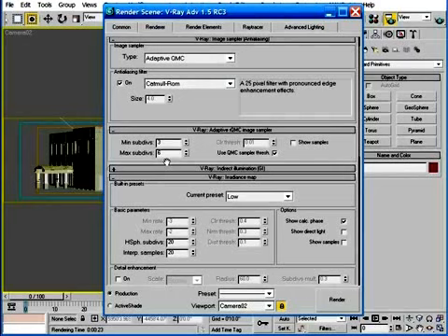I'd also recommend not separating the min and max values by more than 3. Doing so can just open VRay up to incorrectly guessing where in the scene you need more detail and where you don't need as much detail.